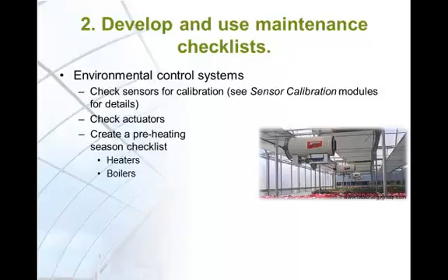Flames on burners should be blue. Yellow tips indicate incomplete combustion, and will cause soot. Unstable flames indicate drafts and possible leaks, allowing damaging gases such as ethylene and carbon monoxide into the greenhouse.